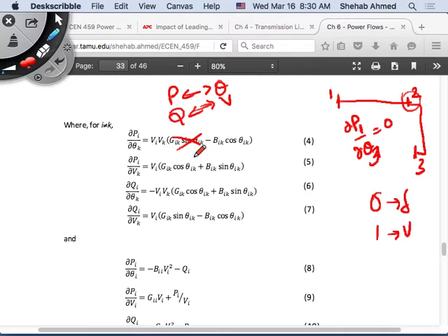Also, what other thing did we assume in a power system? Are we going to design a power system such that we are operating inefficiently and burning power in the cables? No. We're typically going to design and select cables that have very low resistance, if we can. Of course, this mainly applies to transmission and subtransmission and maybe distribution before it comes inside the building.